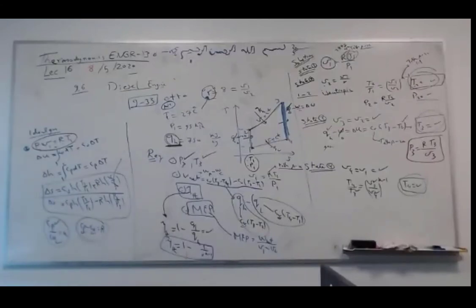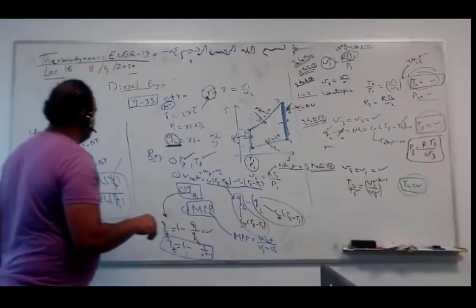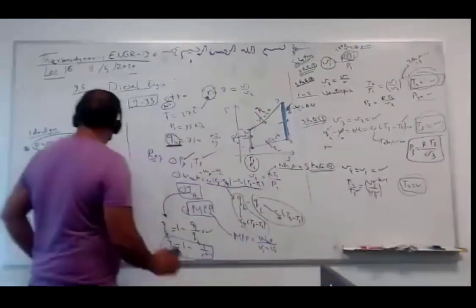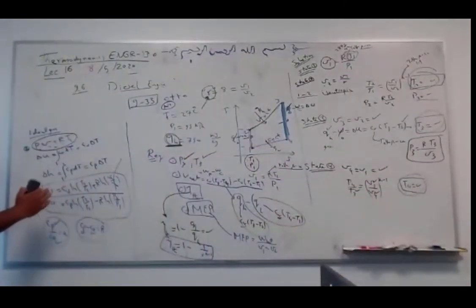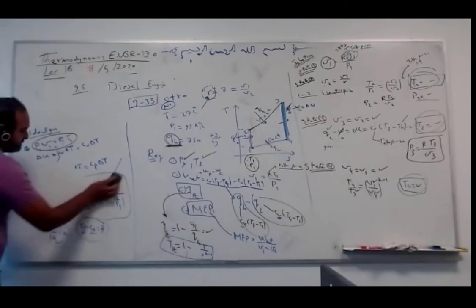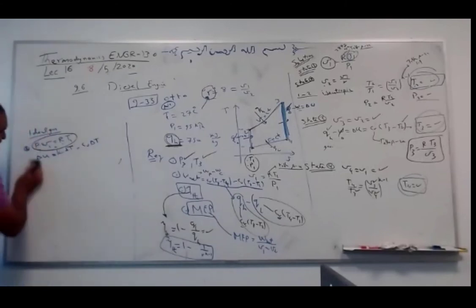Okay, guys? Any problems? Any question? So remember, this is called ideal gas. Do not forget this: Cv delta T, Cp delta T for h, constant pressure, constant volume, delta S. And if it's isentropic, put this 0, which we simplify to PV^k or TV^(k-1) and so on. This is called the isentropic relation if it's 0. If it is not, you're supposed to obtain it.